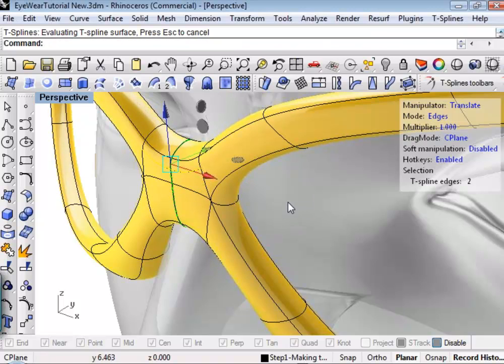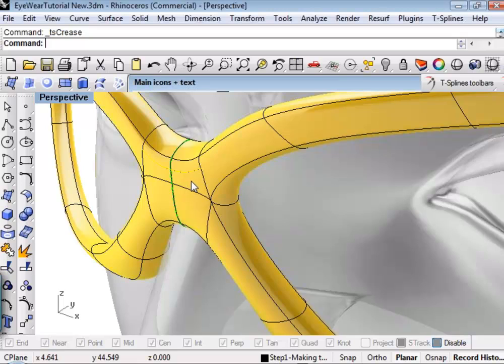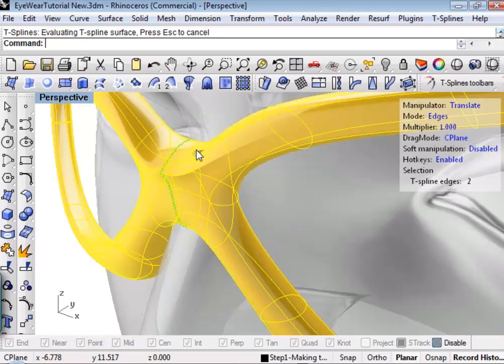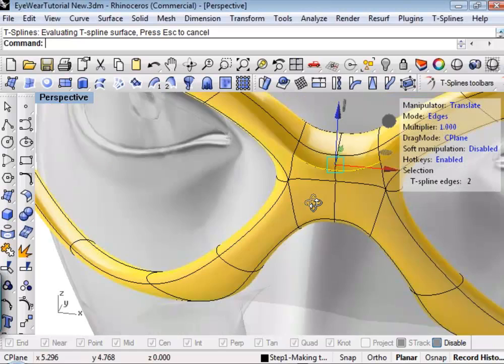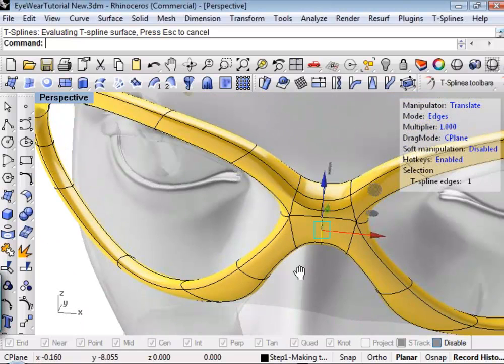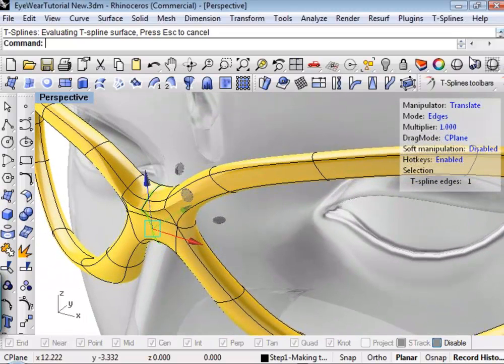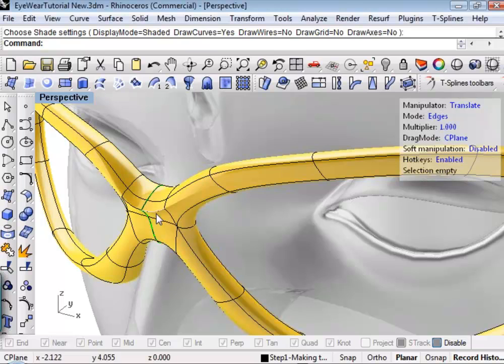And if I were to crease this, which I don't particularly like to crease myself, I'll do it, and then let me show you why I don't like crease. So now that's creased. If I pull this, you'll notice I get a nice sharp edge on there. Now, the thing you need to remember about crease is it takes 2 faces for the crease to fade out. And if I shade this, notice my original crease is here.